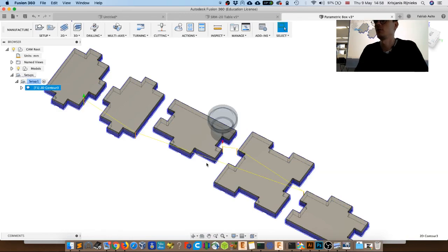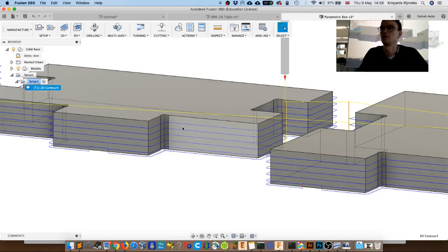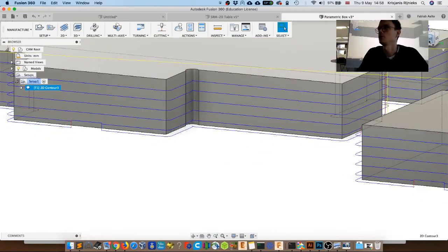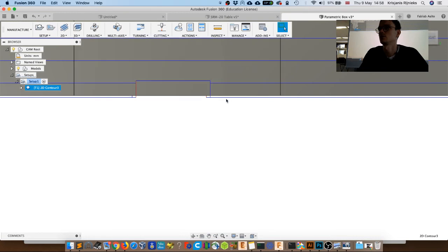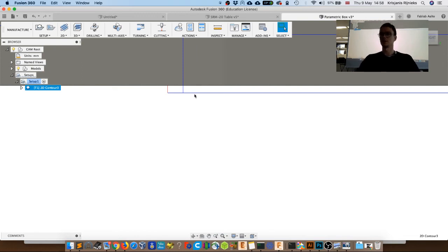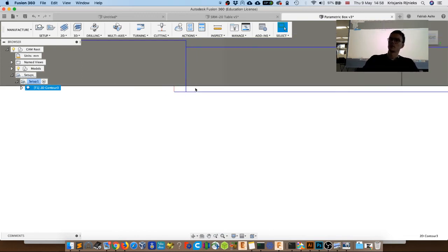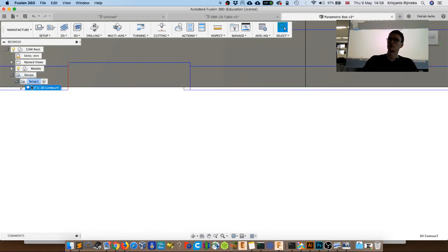It's gonna give me 2 paths. You can see the blue lines. These are actually the lines the tip of the tool is going to travel through. And if you look from the right side, in orthogonal view, you will see that the last blue line is a bit below the actual model. So this is the actual stock to leave along the z-axis. Axial stock to leave.